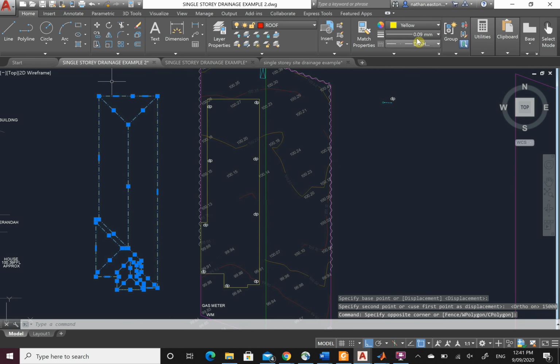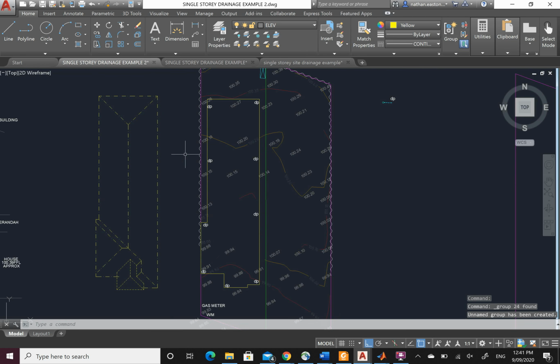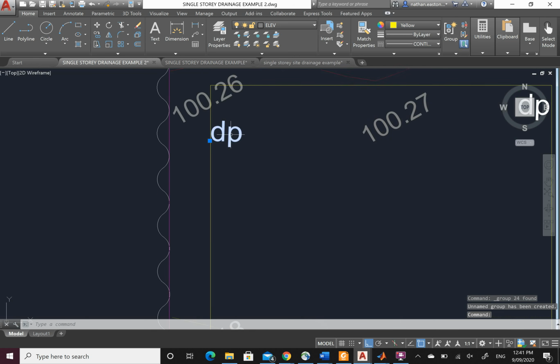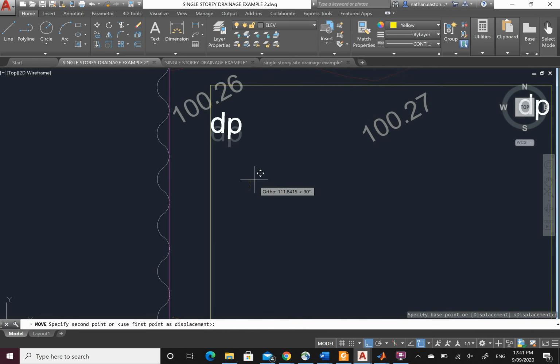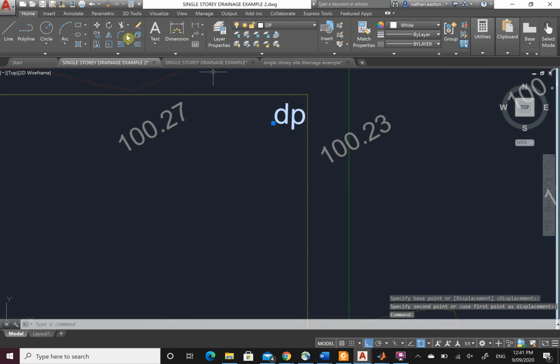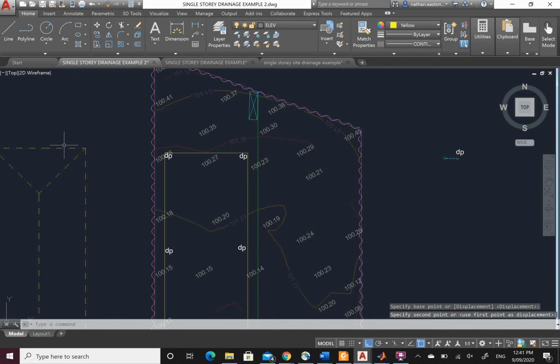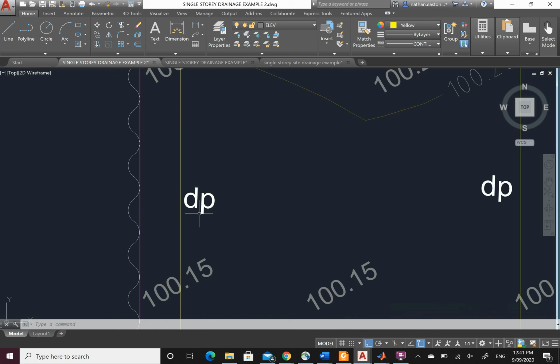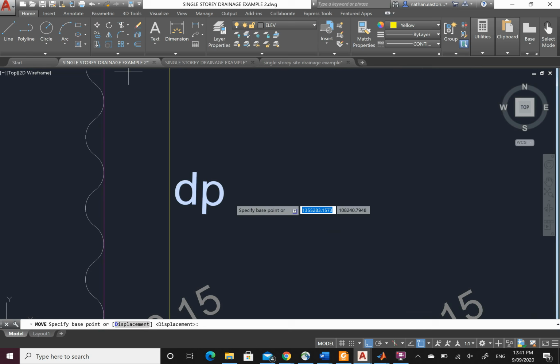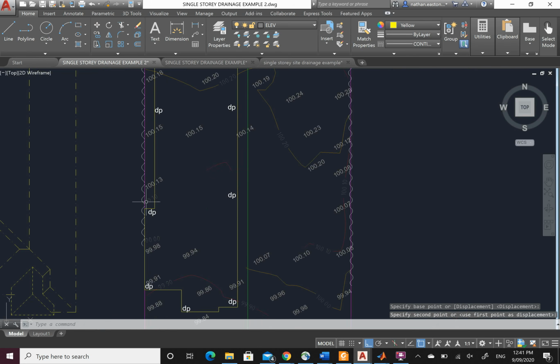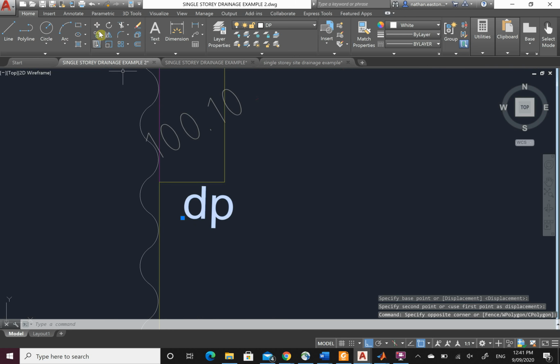Now I can select that whole thing and group it by itself. So where are my downpipes sitting? Well, my downpipes are effectively going to sit on the inside of my walls. Why is that? Go have a look at your house. You'll see your eave line, the outside of the house. You have a gutter on it, and the downpipe will bend back and come down the wall of your house. They don't just hover outside. They all bend back towards the walls, which means my downpipes sit here somewhere.